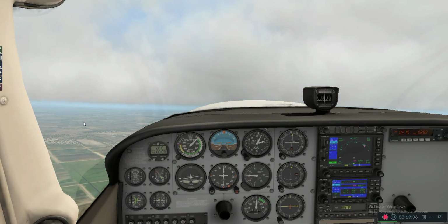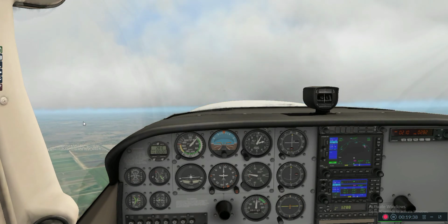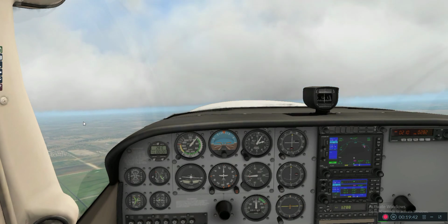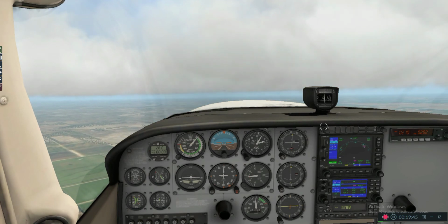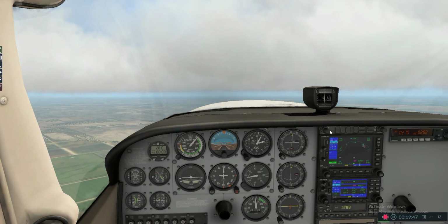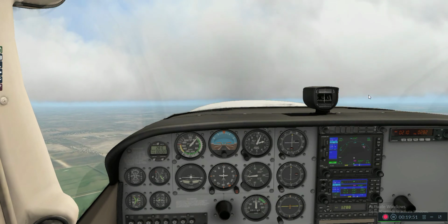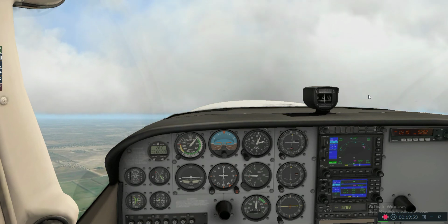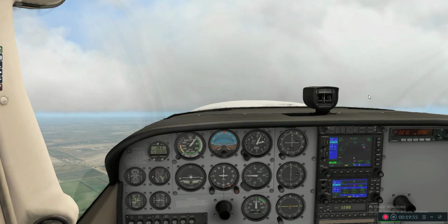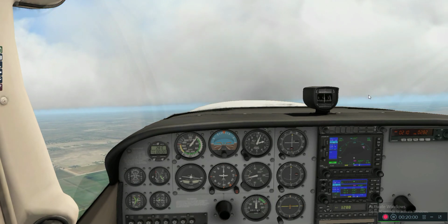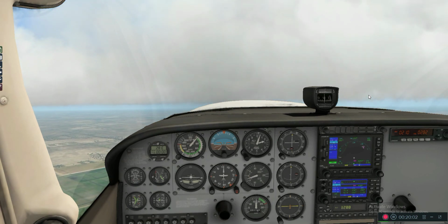It used to be common to practice stalls listening to the stall horn the whole time. But that's been sort of retired. It's considered a little more dangerous. And it's not a good habit to fly around listening to the stall horn. It's not how you would really do slow flight. If you were slowing down, say in the pattern for another plane, or ATC asked you to slow down for separation, you wouldn't fly around with the stall horn on. You would fly at 50 or 60 knots.